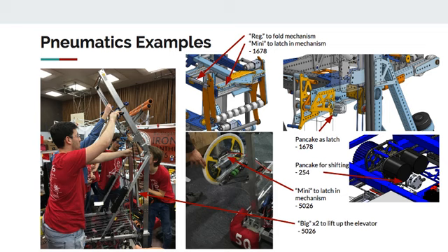I would say nowadays all the top teams consistently have pneumatics on their robots. I don't think there's any reason you shouldn't design it, but the reason you may not is because of bandwidth or weight, especially for less top teams. If you go to a competition here, I'm not sure you'd see it, but if you were to go back to Virginia, you would. There's some definitely reliability stuff that goes along with them.